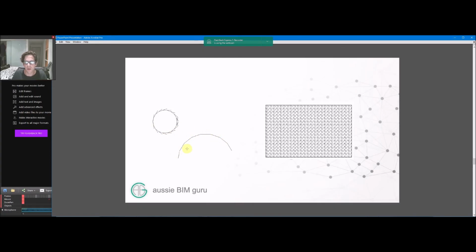For people that know computers and game design and how meshes work, you will know that there's typically not really such a thing as a perfectly curvilinear surface or line. It's always faceted, approximated, or triangulated to some degree, but Revit makes it painfully obvious sometimes. You can see here some of these circles have actually feathered after each line because Revit's hit its minimum line size for those segments of the circle, and it actually hyperextends them to reach its minimum size. So just be aware of that when you're doing curved surface patterns.